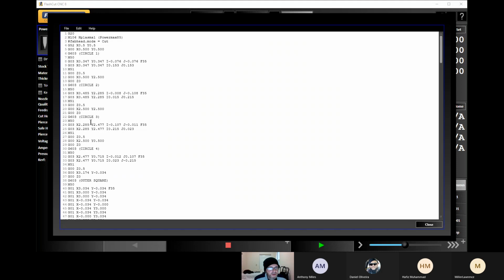Okay. Now, I know this was a lot to take in. This won't be the only day we go over it, but I just wanted to introduce the concept of the G52. And the important thing to remember is that it gives us the ability to basically move a part wherever we want, and wherever we move that part to, it acts as a 0-0. So we don't have to make any alterations to the programming of the part. And tomorrow I'll show you how we can do this manually.